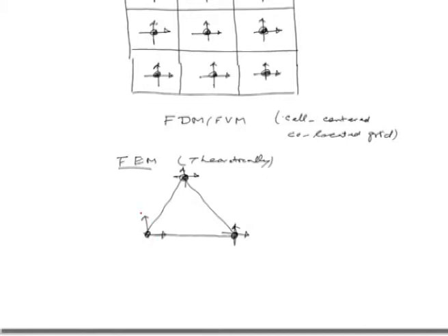Why is it theoretically? Because there are certain requirements which the finite element interpolations should satisfy for pressure and velocity, which would not allow the use of shape functions of the same order for both pressure and velocity components. But just for the sake of explanation of co-located grid in the context of finite element, if you were supposed to choose, that is what we have to take there.